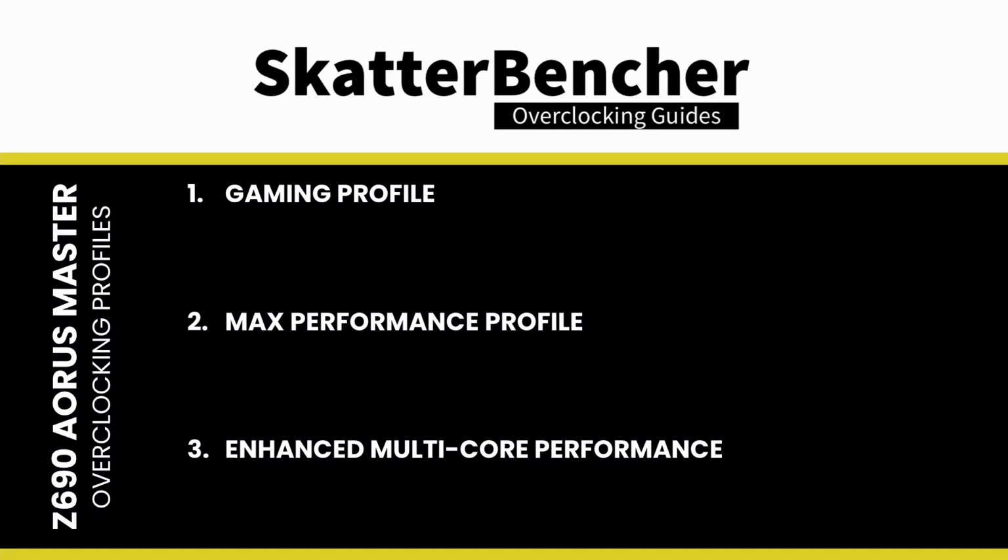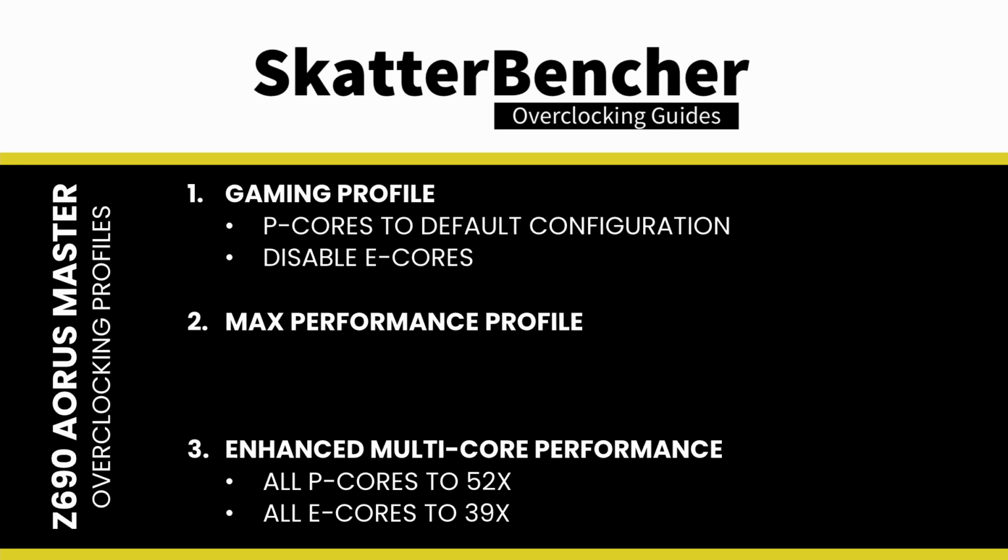Each profile has a different approach to performance tuning. Enhanced Multi-Core Performance sets all cores to the maximum available turbo ratio. On the 12900K, that means every core will run at 5.2 GHz. In addition, all E-cores run at their maximum turbo boost of 3.9 GHz. Gaming Profile retains the detailed turbo boost behavior, but disables the E-cores.